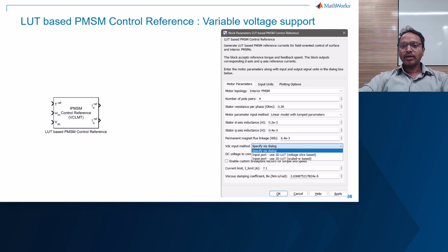When the motor is operated with a fixed system voltage, there is going to be no effect on the ID IQ lookup tables since the voltage limit curves at any given speed only depend on the speed. But in practical applications such as automotive traction applications, the battery voltages are prone to change. When the system voltage changes, we need to account for the change of shape of the voltage ellipse with respect to the updated voltage when drawing the constraint curves and while computing the intersection of the curves for computing the ID IQ lookup tables.